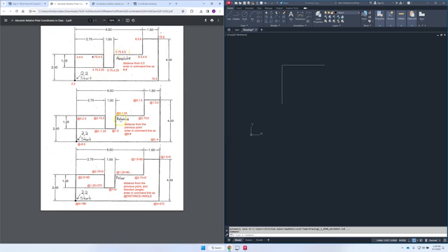With relative inputs, you can see down below, if we type them into AutoCAD, we need to remember to add the @ symbol first. So, our start point was 2, 2. With relative, it's always from where you start to where you're going, just that single step. So they are not additive. So this 2, 2, that's what you'll type in AutoCAD to start your drawing, and I'll do an example on the right-hand side of my screen.